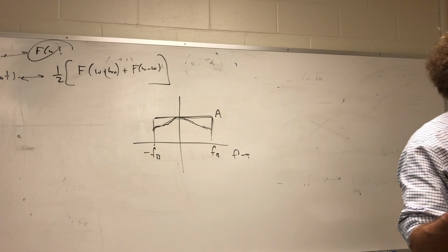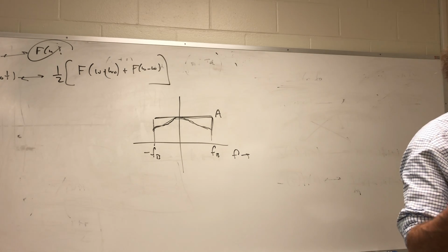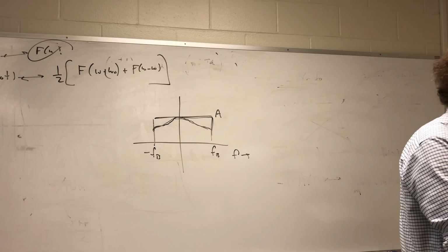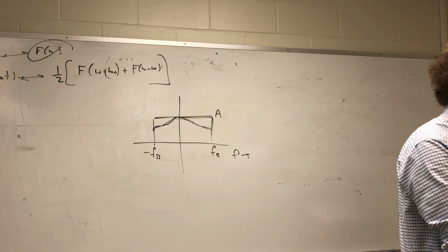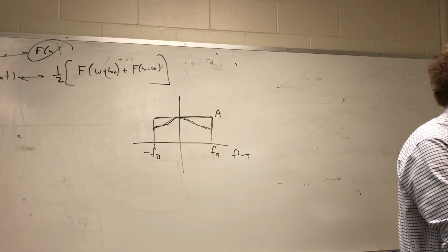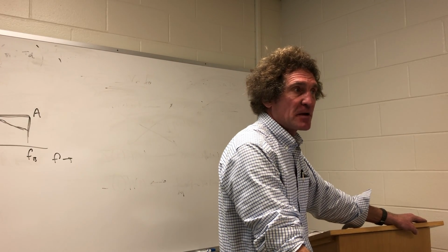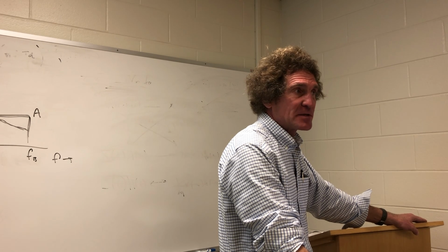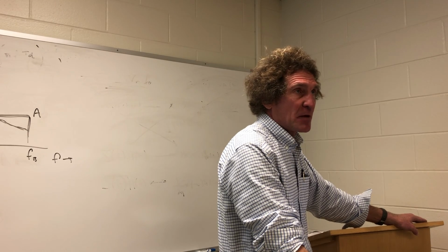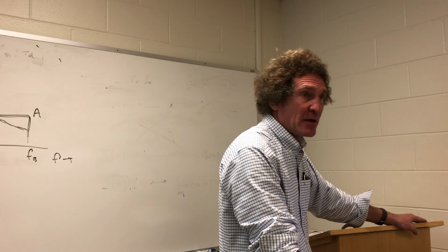All right? Some of the stuff that they're doing at intermediate frequencies, what's intermediate now? 365 kilohertz? I mean, what's your IF for your radio when you have your radio lab? 200. 200 what, kilohertz? Yeah. Well, typically a real radio would do 370 kilohertz for AM, yeah. That frequency is not that overwhelming. That's doable for even a relatively cheap op amp and stuff like this, but when you're talking about 30 megahertz and higher kind of stuff, it becomes a problem to get any bandwidth that's substantial.